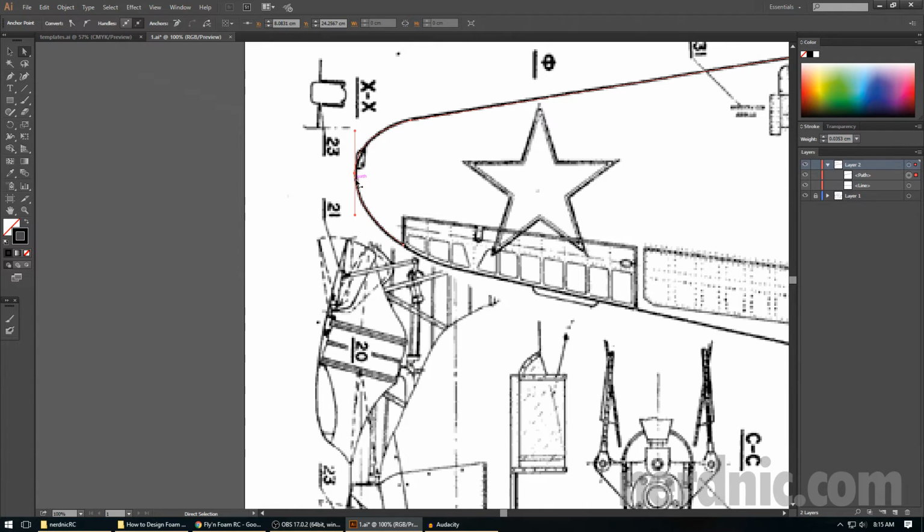In this case, I could extend that anchor and keep bending. Other times you will not be able to just start over. And what I do, once you've started your pen tool on that second one, to get off of it, to break off and start over, just press the A key, which brings you to your select tool, and then you can go back with your pen tool and finish it off. Okay? That's how you'd break free from that.